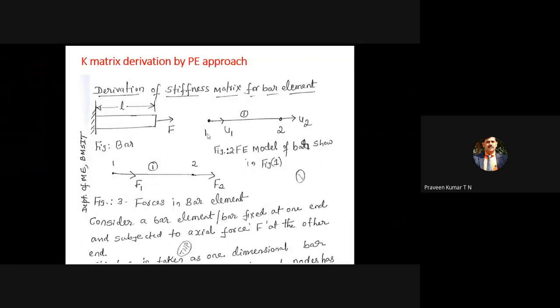Now, even in heat transfer problems, the same type of element is used. We have a two noded heat transfer element where the temperature at node 1 is T1 and at node 2 is T2. At one side, T1 may be T0. It may be exposed directly to some heating element, or if it is an internal combustion engine, the temperature of the inside surface of the cylinder will be referred to as T0. The outside surface temperature of the engine may be T infinity. That's the only difference.